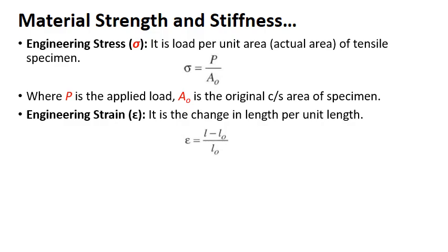For this you have to understand the concept of Saint-Venant's principle, but I will leave that part to you. If you look at the dog bone specimen, it has a shoulder for gripping. The diameter is very large compared to the specimen diameter, and there is a taper from the shoulder to the specimen diameter, with a fillet. Because we have a geometric discontinuity here, there will clearly be stress concentration. So when you pull it, you will have stress concentration in the area of the shoulders.